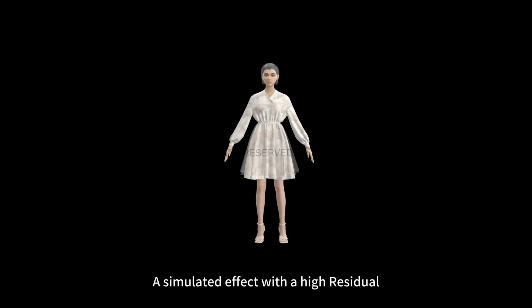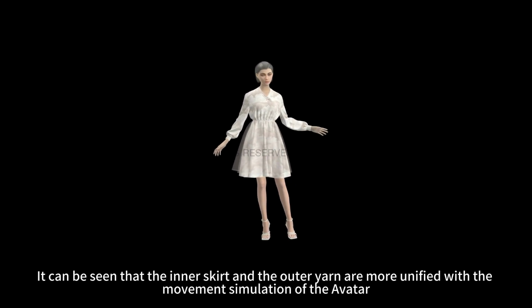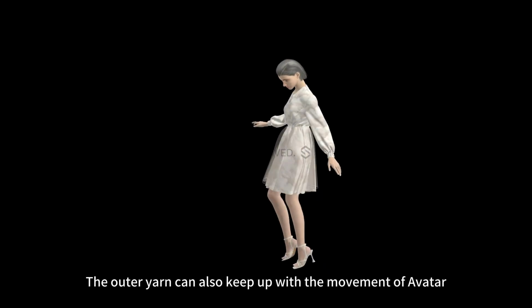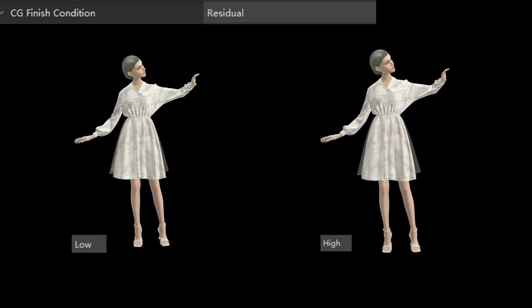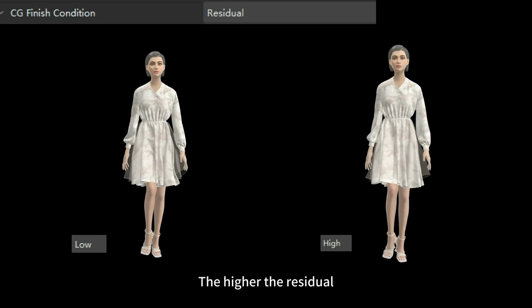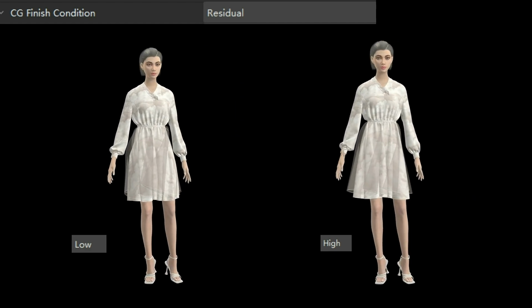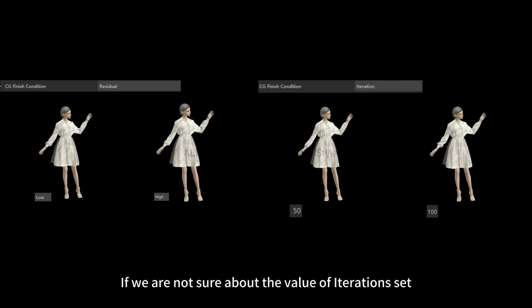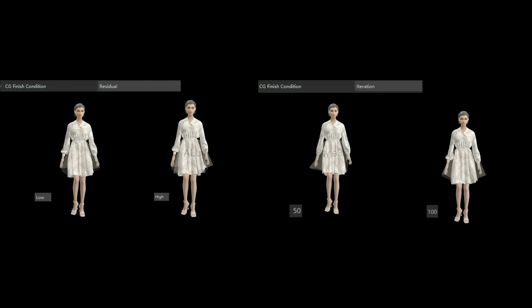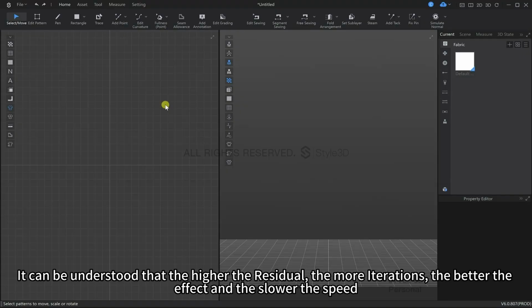A simulated effect with a high residual. It can be seen that the inner skirt and the outer yarn are more unified with the movement simulation of the avatar. The outer yarn can also keep up with the movement of the avatar. Get conclusion. When the particle distance is different in the same animation, the higher the residual, the more consistent the effect. The more consistent the effect between different patterns, the higher the corresponding number of calculations generated. If we are not sure about the value of iterations to set, we can set the residual. It can be understood that the higher the residual, the more iterations, the better the effect and the slower the speed.